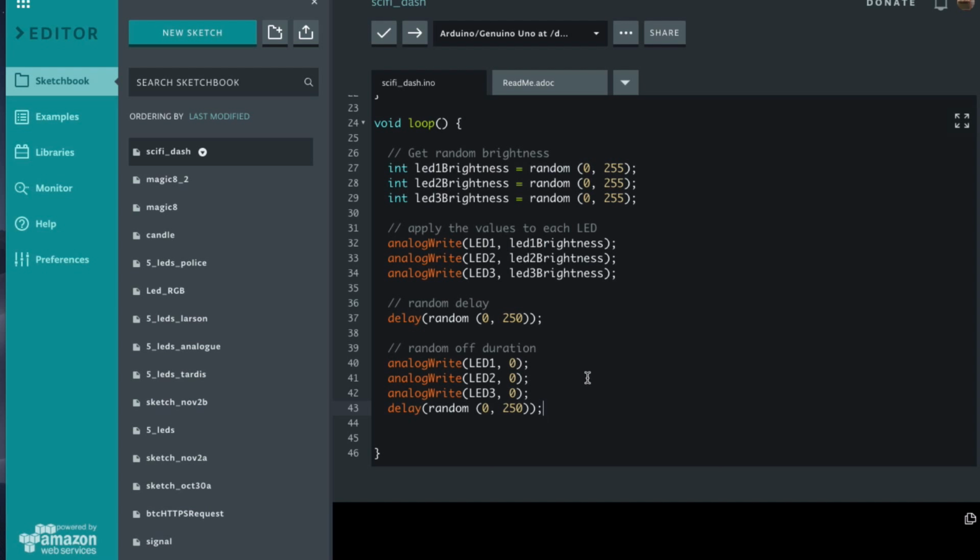Now you'll notice that when the LED is blinked on and off very, very quickly, it looks like it's on full, or it's on but it seems dim, and that is exactly how this brightness works. It's PWM, so it's not actually sending an analog value. What it's doing is sending the current and turning it off so quickly that the eye cannot detect it, and that's because of persistence of vision. So because it's turned off and on so quickly, it looks static to us. It looks like it's just on all the time.